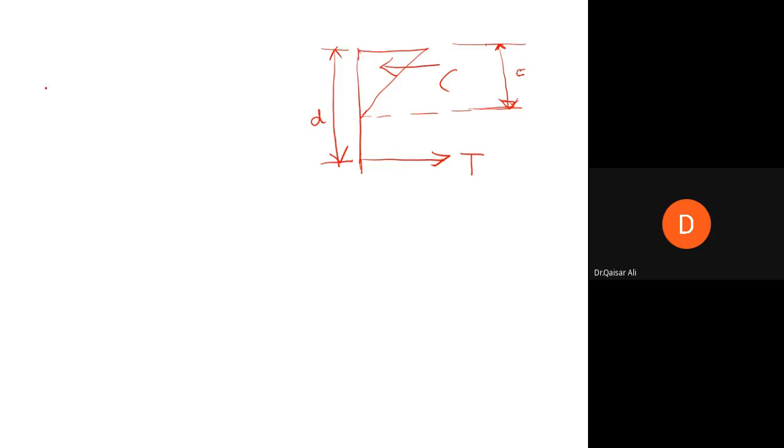Okay, C is now equal to what? This is 0. This is fc, fc equal to 0.45 f'c. C again is (fc plus 0) divided by 2, because you have the maximum value fc here and 0 here. So 0.5 fc will be the average stress.